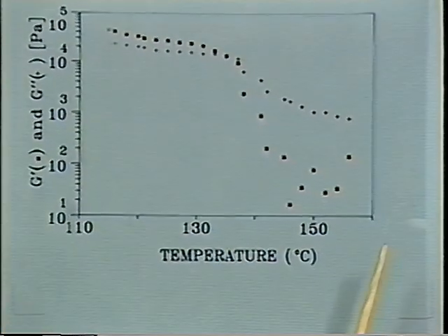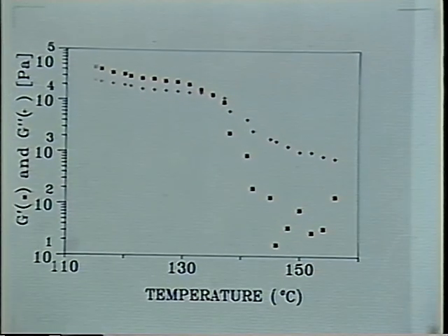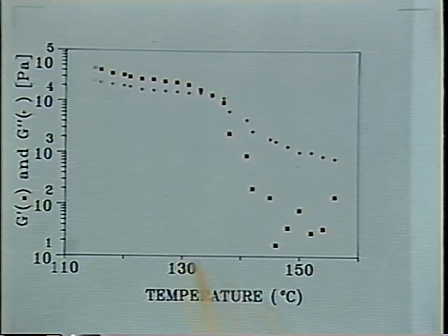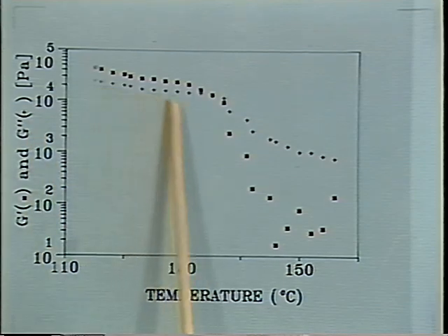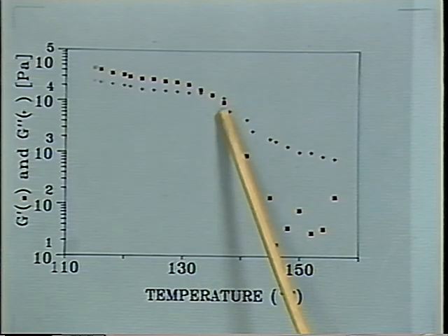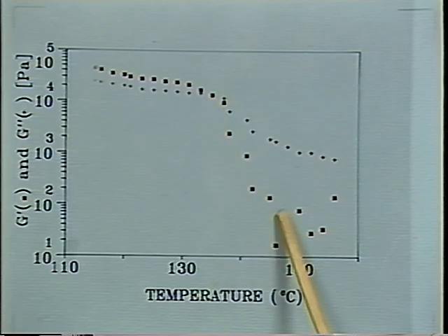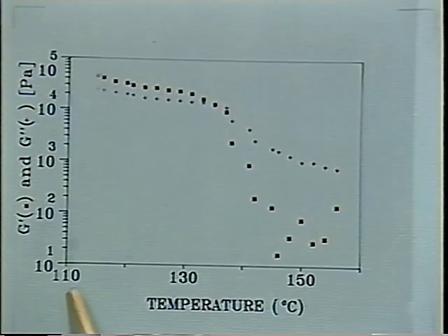The rheology of that system is, well, showing a very nice transition when we go from single phase to two phase or vice versa. Here's the modulus. In a heating experiment, here we have two phase, very high modulus, and then as the sample undergoes a transition to the single phase, the modulus drops. We are far above Tg.